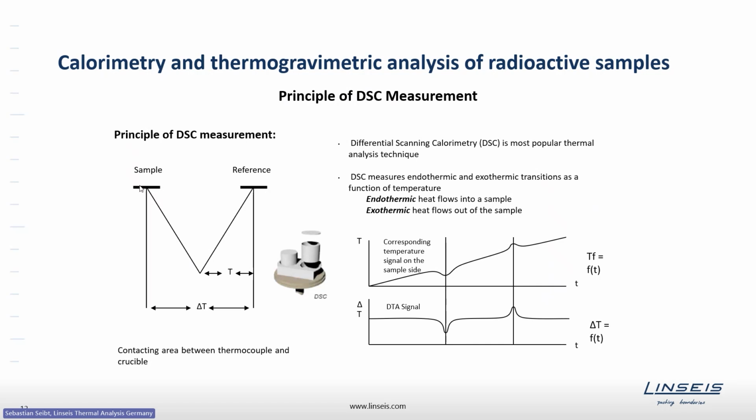And what the system does is it senses the temperature of the reference and the temperature of the sample by using thermocouples, and it determines the difference in the voltage of the two thermocouples as a differential signal. You have to imagine, as long as the sample does not show any reaction and this complete sensor head is heated, both crucibles, both sides will be at exactly the same temperature. There will be no difference in thermal voltage between the two thermocouples.